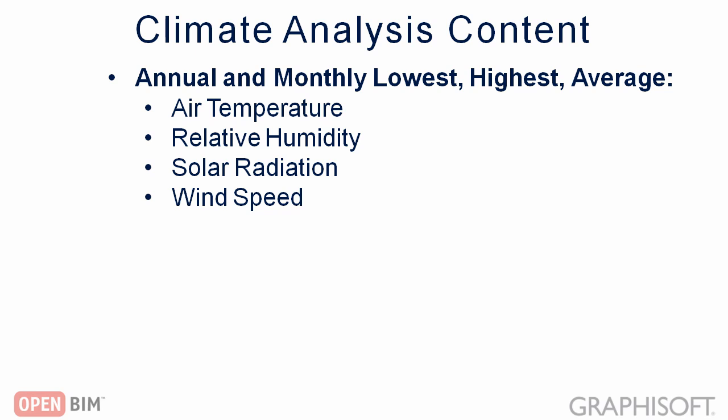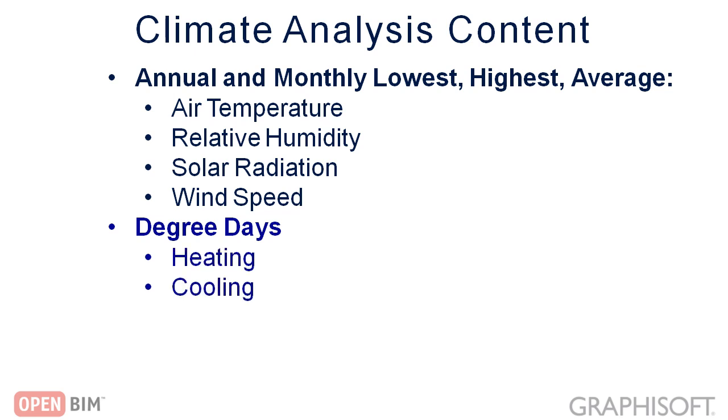We will also present how to obtain such weather files and how to produce the above-mentioned annual and monthly statistics from the weather file. We will also present how to calculate the so-called degree days using the above statistics. Later, this information will be used to help design decisions regarding the architectural solutions, for example, the building shape, zoning, materials, etc., as well as the heating and cooling systems in the building.